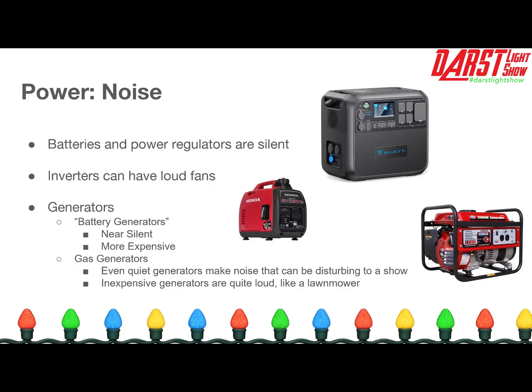The downsides are you have to charge them or keep them charged when not in use, which takes some maintenance of the batteries and all that kind of stuff. And then the other part is they're not weatherproof. So if it's raining, you're going to have to protect these in some way. Say you put a plastic bag over it, well, now you've limited the airflow, so it could be more prone to overheating. So pros and cons to using the battery generators.